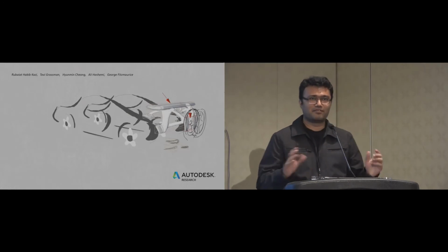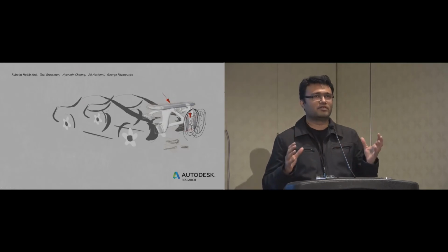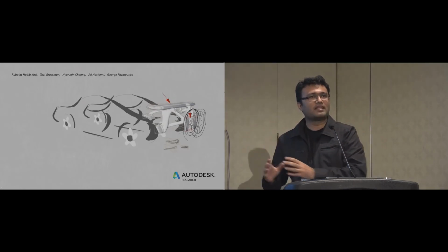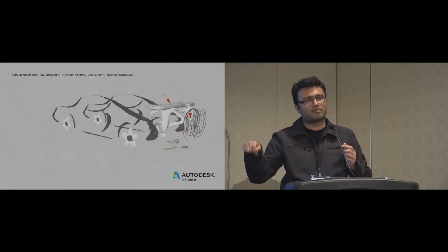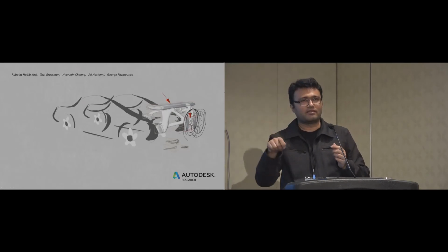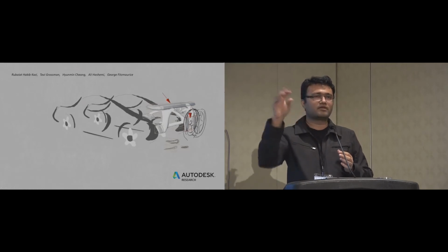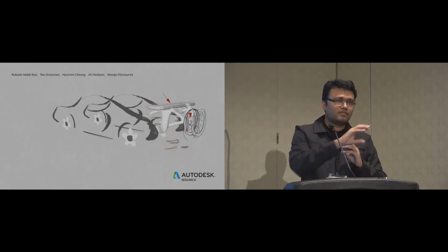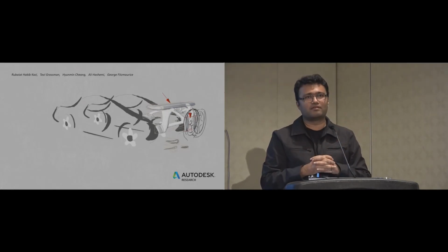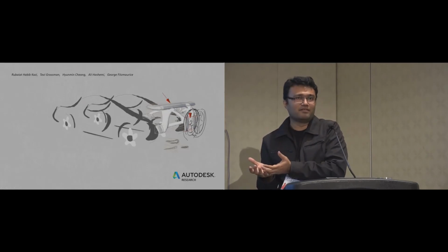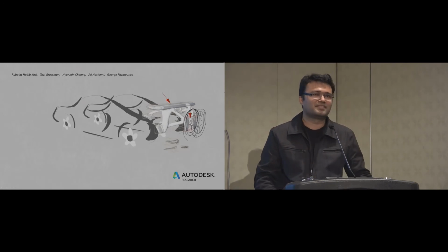Yeah, that's an excellent question. I don't have answer to all of your questions, but I can say that it's up to the designer how big the holes they want to leave. In my case, for the bike example, I left big enough holes. But I could have easily defined interface objects and some of the other details of the bike. I want a shape like this, or I want a shape like this. I could have done that using this interface, just like I have defined the other different components. I could use voids and other things to define a shape that's something I'm looking for. So again, in this case, I left big holes, but in other cases, you can leave small holes so that you can get more predicted results.